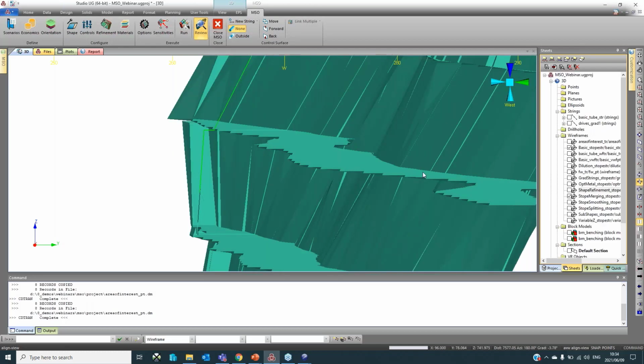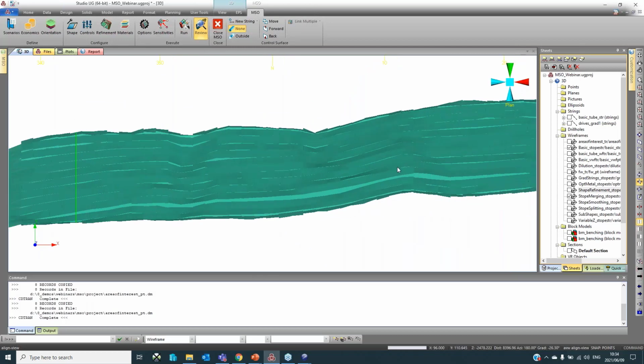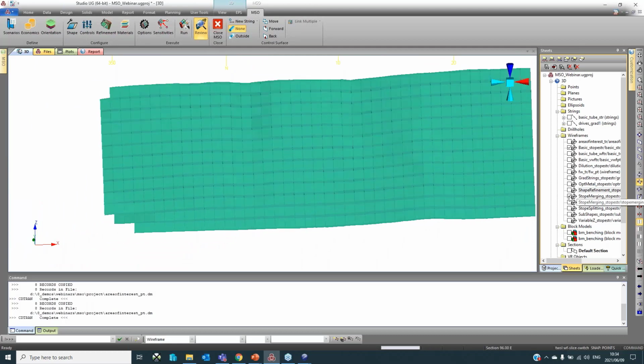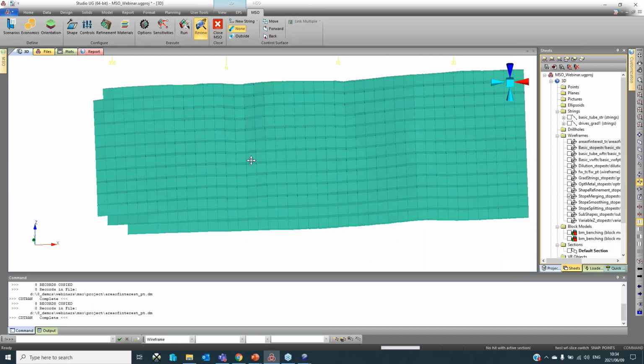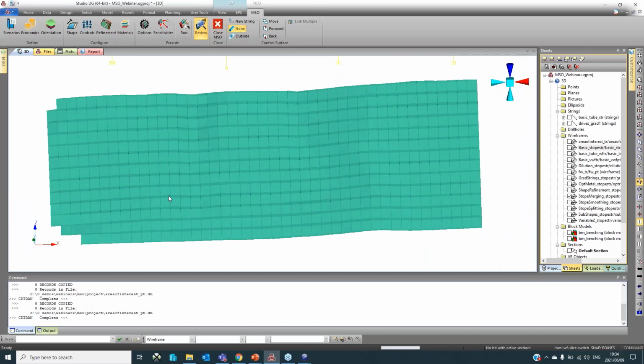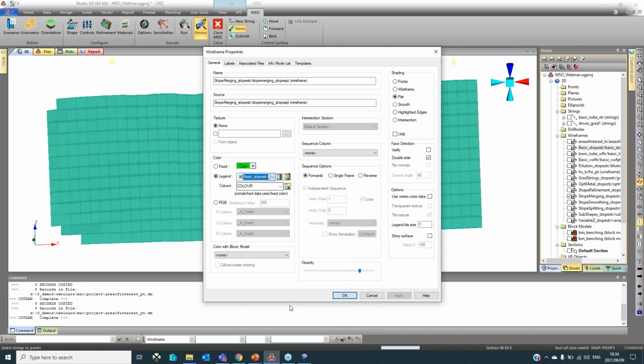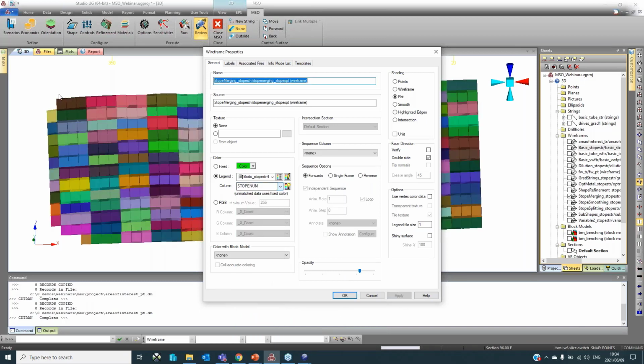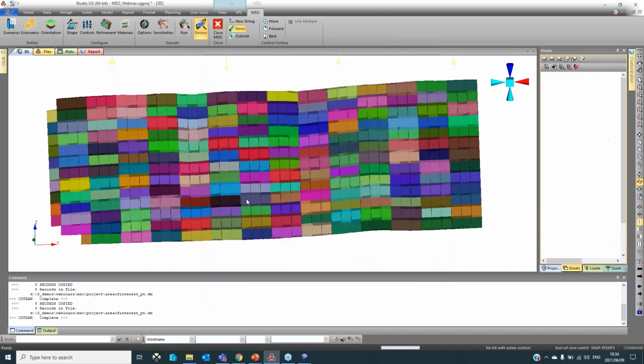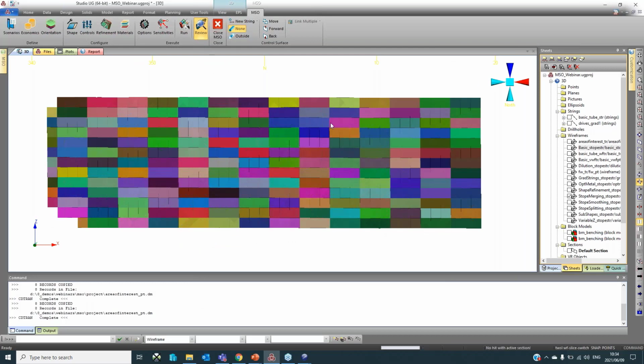Next one is the stope merging. As I mentioned before, the stope merging doesn't affect my stope shape. They will be exactly the same. The difference is that we are considering 3 volumes as a unique stope. So if I apply my stope number legend to this field now, we will see that each 3 stopes on the basic scenario is now a unique stope in this one. So we can see the identifiers here.